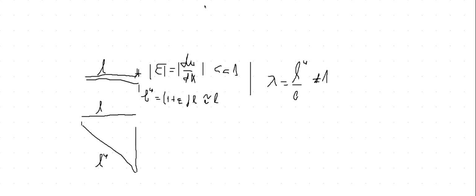If I take a small deformation theory, epsilon will be basically equal to 0, because I move this end vertically and that end vertically, and I don't see any difference in the x direction. But if I take lambda, L phi is certainly not the same as L, and I can take into account the stretch.